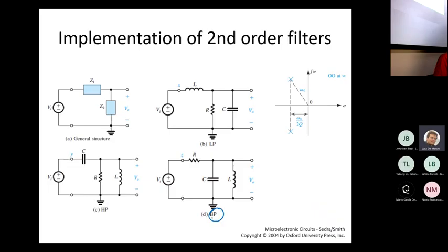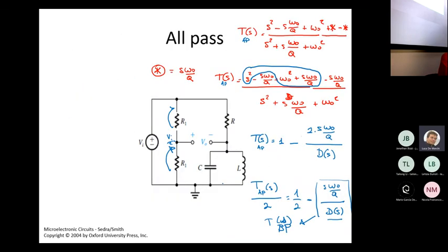Here it is: resistance in series with a parallel between capacitance and inductance. We pick up the voltage at this point. So the voltage drop between this node and this one is coincident with the output of an all-pass function. We can realize the all-pass circuit in this way.